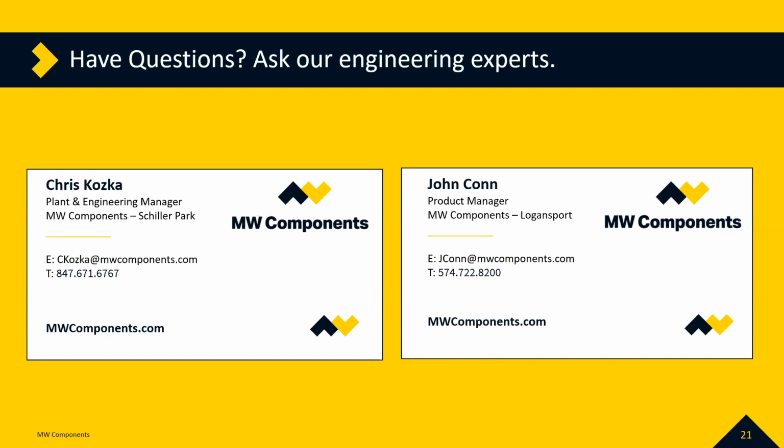That's what I'm assuming it is, but definitely you could reach out to me, maybe I could talk it over the phone with them when I get a little more detail, but based on that question, it's the only thing I could think of. Yeah, it could be a case where the torsion spring itself has gone beyond what it was designed for in trying to pick up more load. Just a simple body diameter or even a wire diameter change would allow it to flex more without binding up.